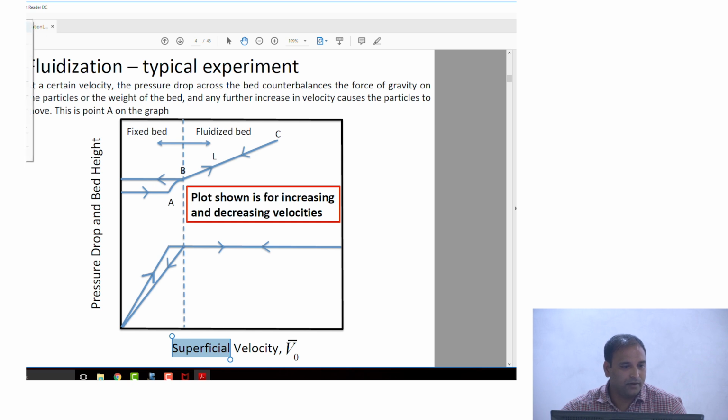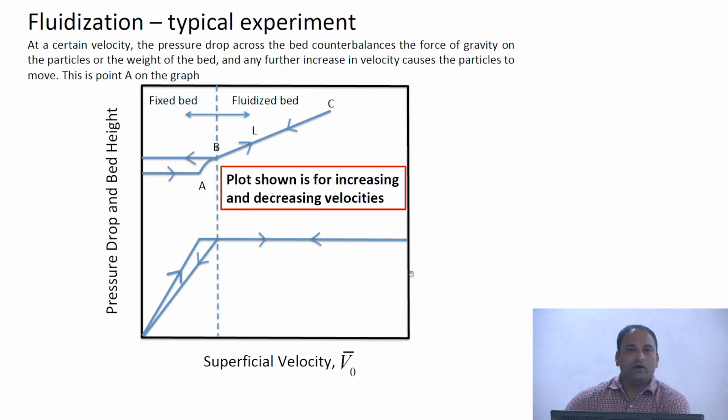when you make a packed bed, what do you think the initial line will depend on? The initial line varies in this way, that's your initial increase. So why isn't the slope a little steeper or a little smaller? What does that depend on? It depends on the way you pack things in the packed bed. It depends on the porosity that you create by packing.